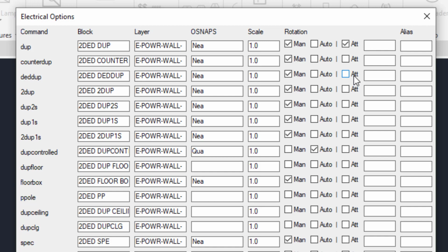And then the last thing is the alias out there. Like I said, the alias editor that I showed you just a few minutes ago is for commands, not the block library. And this is why, because you can add an alias to the block library out here. Once again, make sure that the alias is available and not standard AutoCAD or taken by another plugin. And that's about it for all of this.